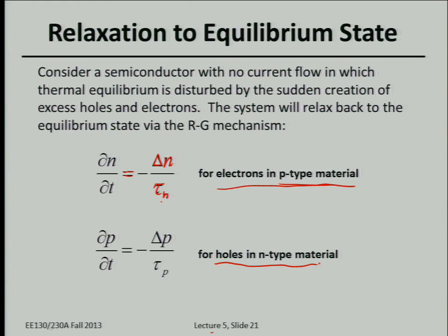The same thing for holes. For the hole concentration in the n-type material, which is the minority carrier concentration in n-type semiconductors, the time derivative of the excess hole concentration is proportional to the excess hole concentration divided by the hole's lifetime, okay, another constant.